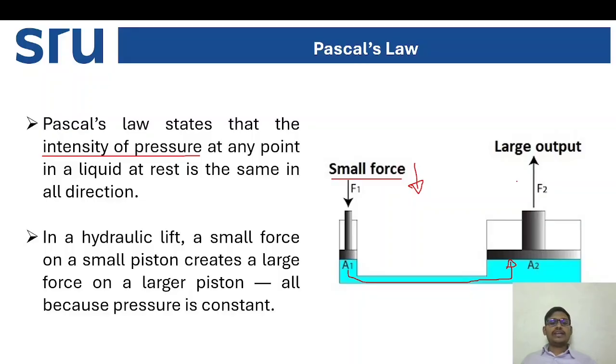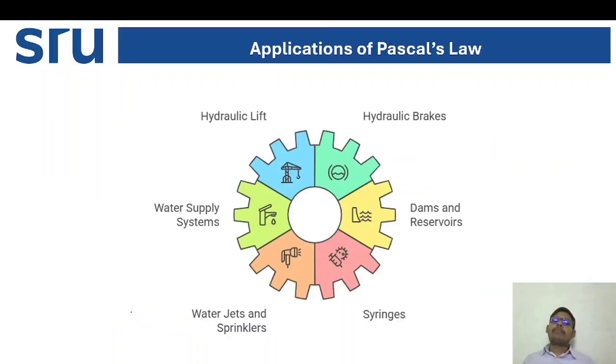So in a hydraulic lift, a small force on a small piston creates a large force on a large piston, all because pressure is constant. Here the pressure is constant, that we have to understand. So what are the applications of Pascal's law?